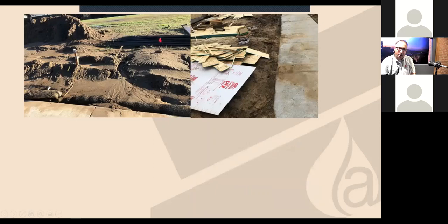This is a wrong BMP to pick from here, because obviously they have a lot of foot traffic, a lot of activity there. That fiber roll was just destined to become destroyed. Probably not a great BMP there. Maybe a gravel bag, a compost sock might have worked better there, so that if you did need to do something, you could pull it out of the way, do what you needed, put it right back in place.